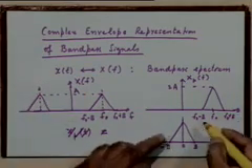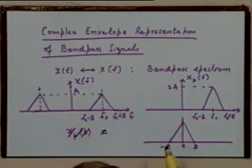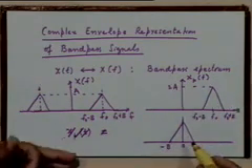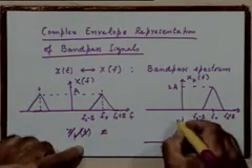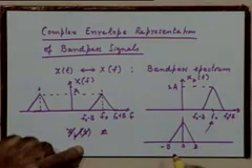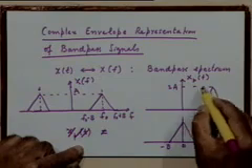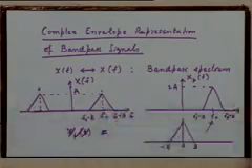In this particular case, because I have taken this to be symmetrical, this looks symmetrical here, but if this was not symmetrical, this symmetry would not exist here. So all I am saying is there is a frequency translation relationship between this signal that I am defining here and the signal xpf, which is the analytic representation of our original bandpass signal.